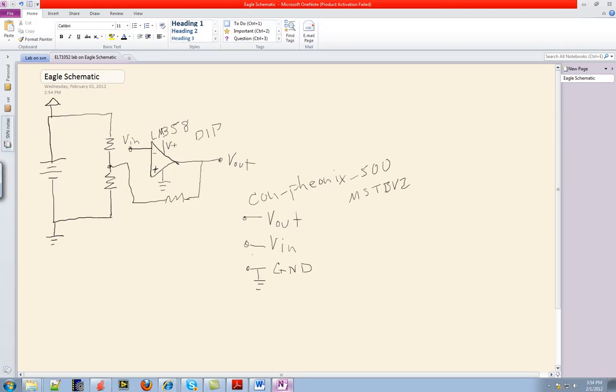So in your methodology, you first want to have a board such as this. You want to have created a schematic on a piece of paper somewhere before you actually start using Eagle. And I've got some sense of what I want to use for these devices in terms of the actual physical device in my hand. I kind of know what I want to use for this op amp. I know what I want to use for these connectors and these resistors.